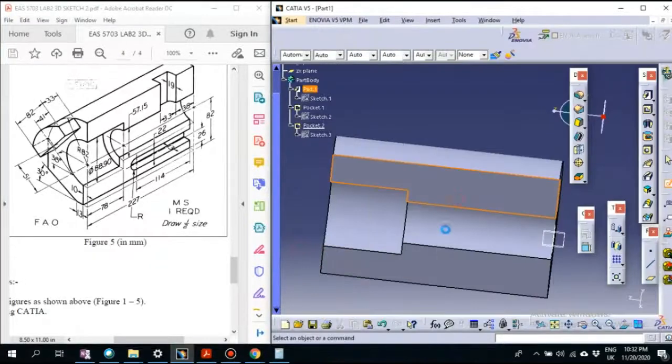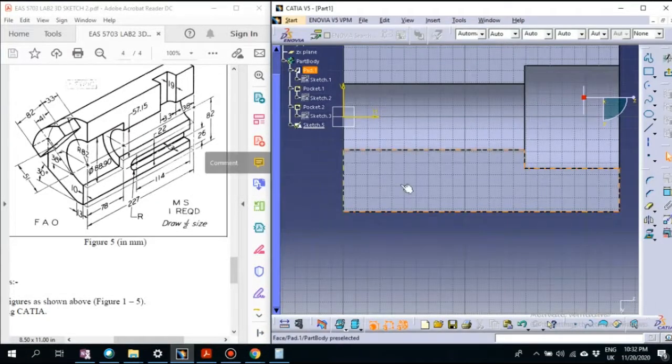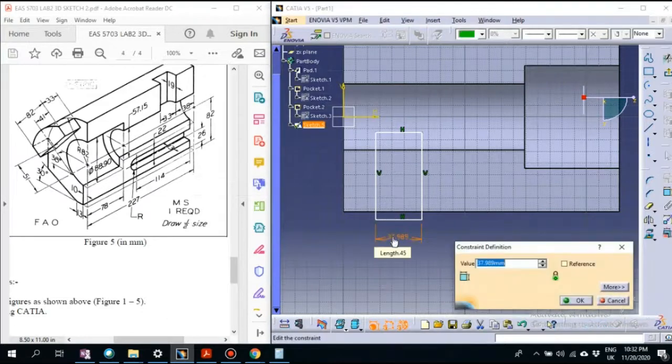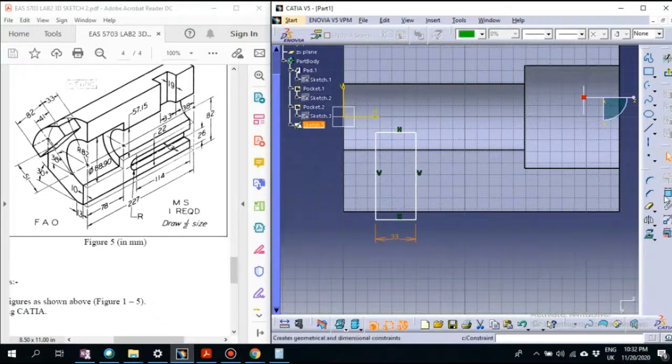Next what we'll do is cut at the top surface of the geometry, so we can create a rectangle there. In this case it doesn't matter for us to create an extra length at the vertical line because we want to cut through the circle.